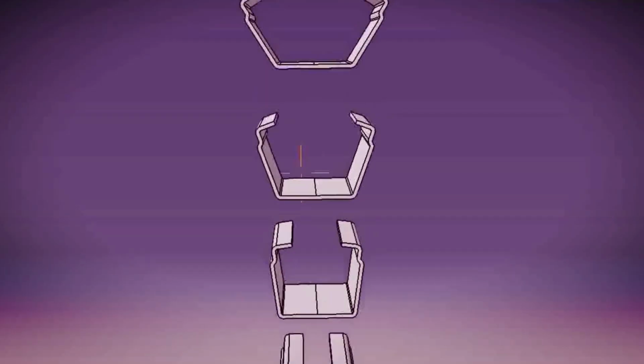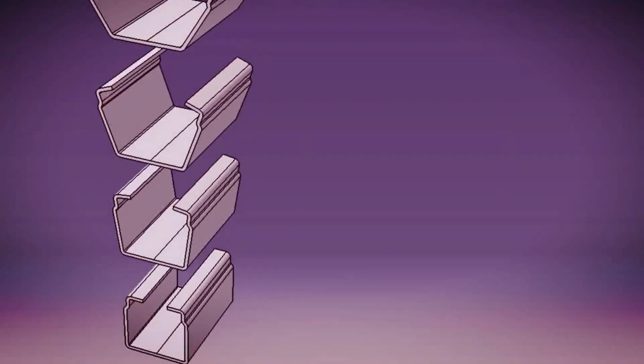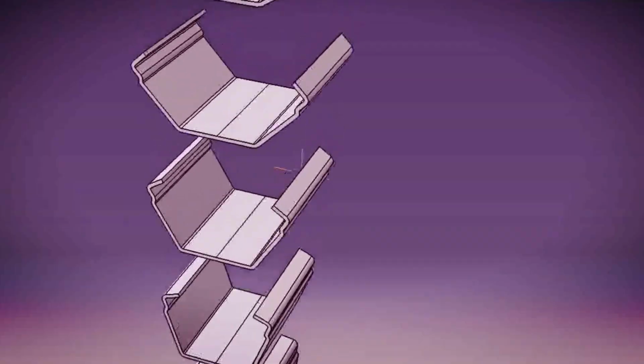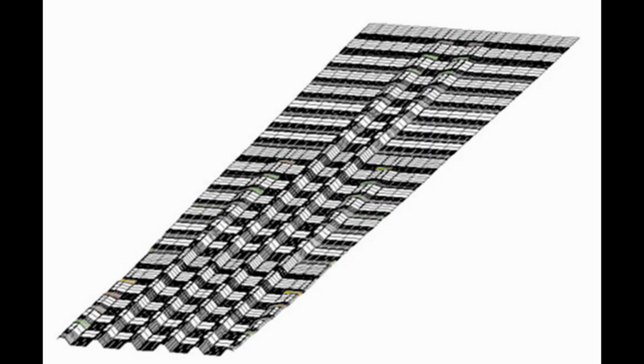And we talked about all this about the method of sequential profiling, which is used for the vast majority of products, including for corrugated sheets. In such profiles, the bends begin in the center and form 1 or 2 waves at once, then 2 more adjacent ones, then another, and so on until the end, until the product is ready.